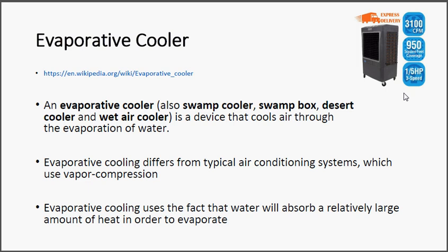It's better for the room environment, because you blow humidified air through the room. Yeah, so the climate gets a little bit better, but also it cools it down quite nicely, and it's very cheap to run. You don't need a lot of electricity to run it. Again, evaporative cooling differs from typical air conditioning systems, and normal air conditioning units, they use vapor compression.